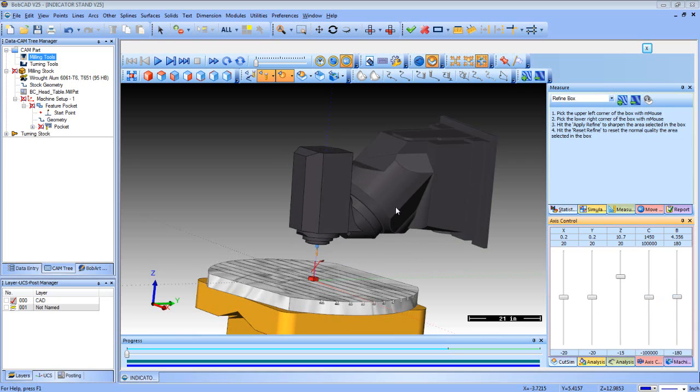The first thing you need to know is the angle from the straight Z of what that head is. In this case, this particular head is a 45-degree angle. What you're going to do at that point is take whatever angle you find it to be and just find the sine of it. In this case, our value is 0.7071. So the sine of 45 degrees is 0.7071. And we're going to use that when we define the direction around the Y and the Z as 0.7071 for both of those, so it defines where that axis is lined up, as you'll see.